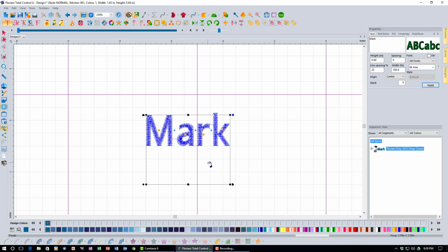So if you see this, it's actually an indication that you've got an extra blank line in there or something like that. So what you want to do is come into your text box, click anywhere, and it usually goes right back to the very end. And if you backspace, it'll delete that extra carriage return, and you can click apply, and now your box will be hugging the text.